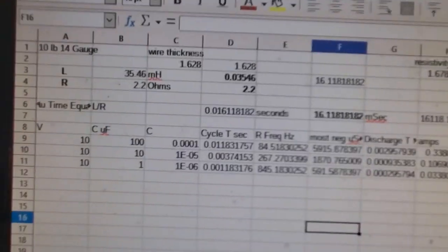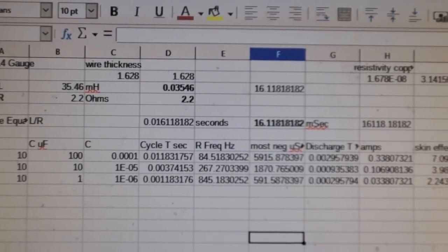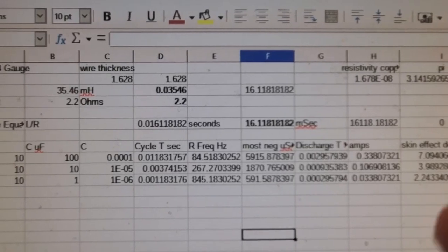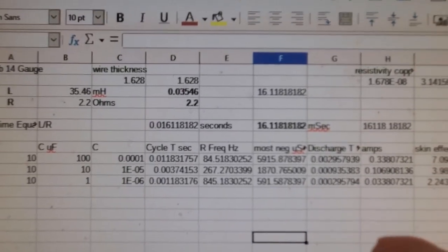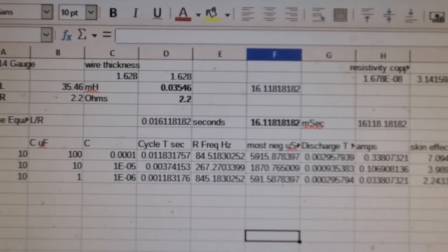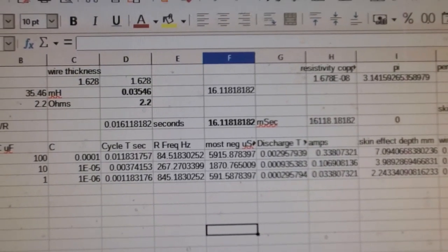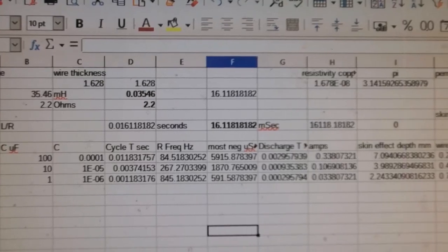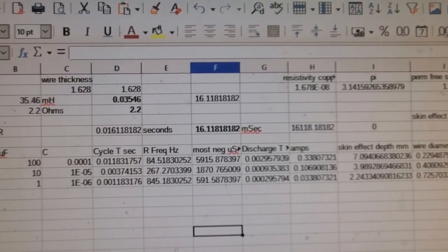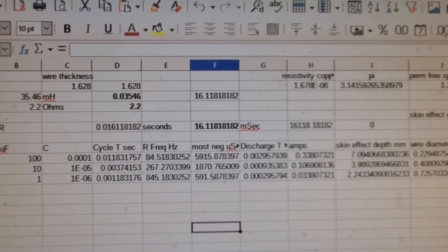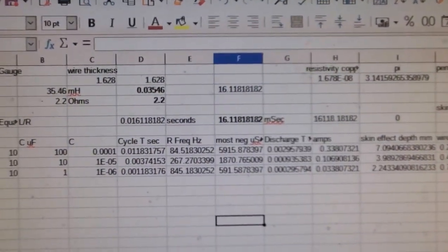But what I'm starting to realize is I might run into all the same issues, and just the fact that I'm using opto-isolation means it might not end up being any faster than the 80 microseconds, 50 microseconds that I'm getting out of the solid state relays now. So it's like, do I really want to do that to myself? And then I also thought about prepackaged opto-isolated gate drivers for MOSFETs, and I might want to go there, but it's sort of, do I need to? And this whole thing is like a wild goose chase. So it's like, do you want to do other wild goose chases?